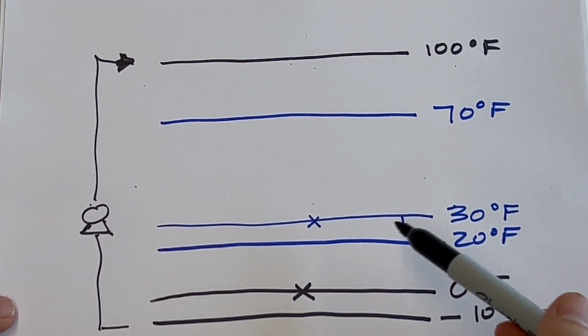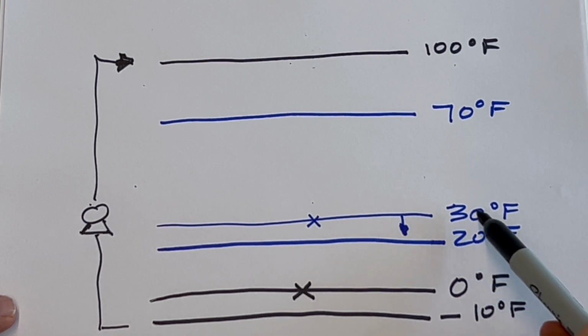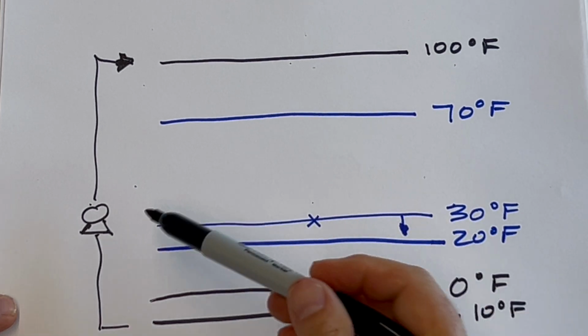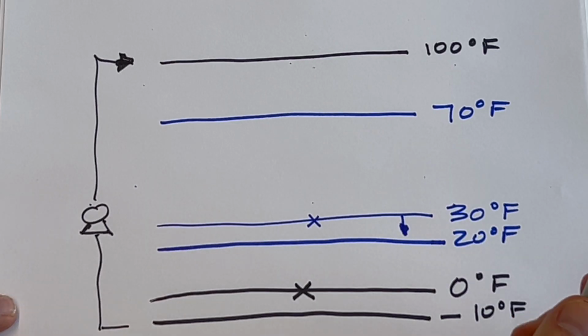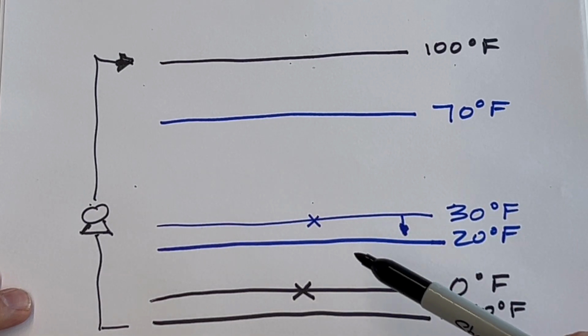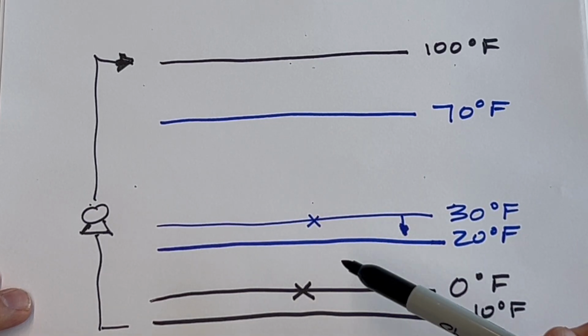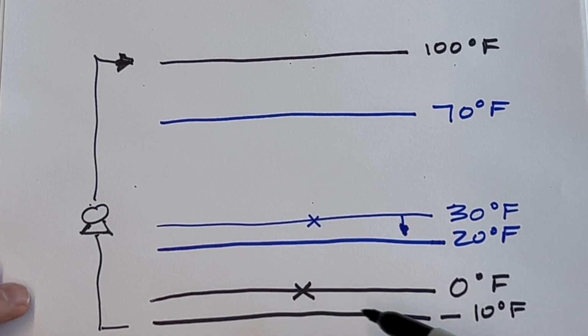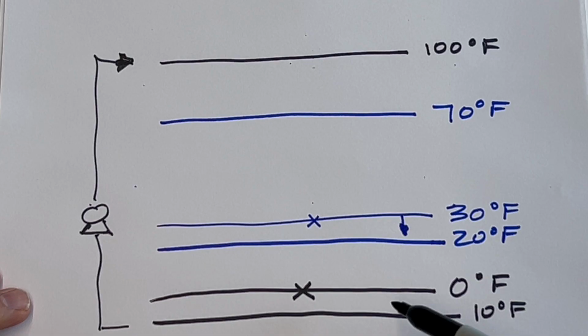So what happens when the outside temperature goes down? The compressor power increases. This means that the heat pump is working harder, the efficiency is lower, and it's using more power. And when it's colder outside, the building is also losing more heat.